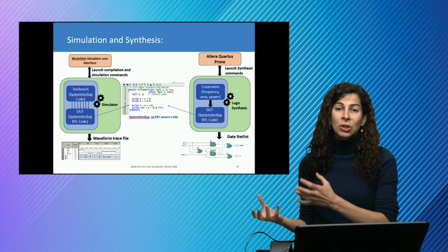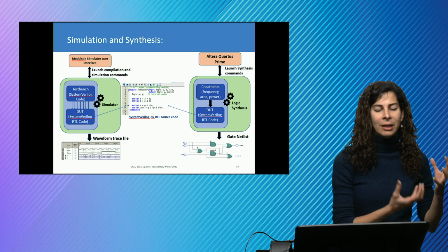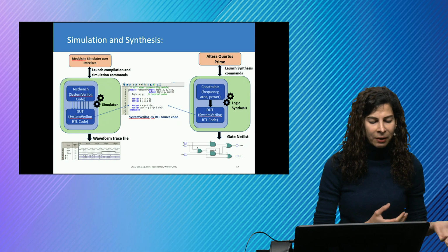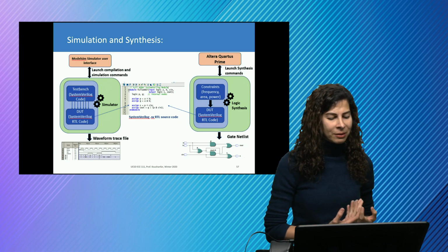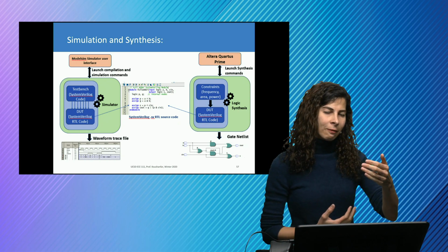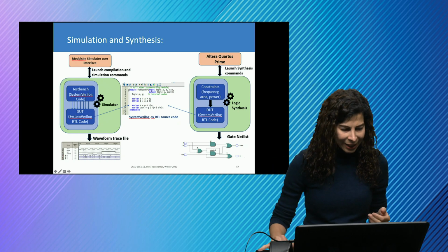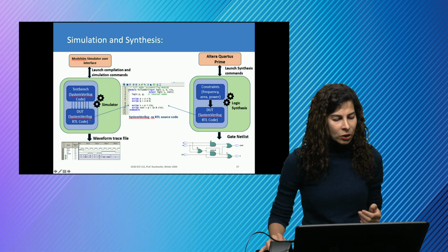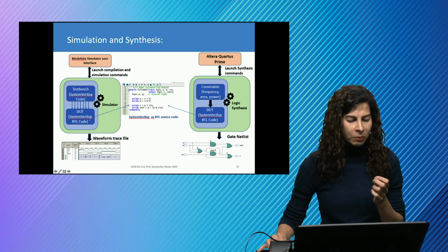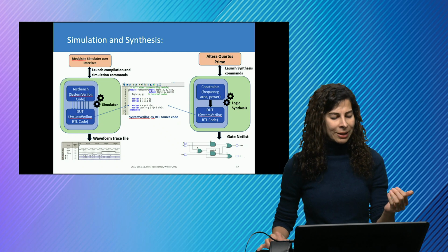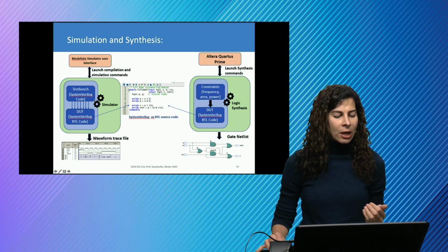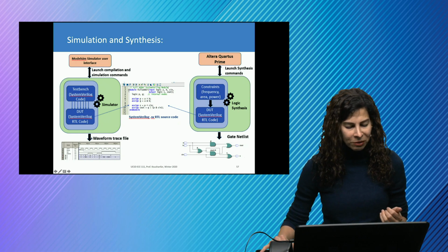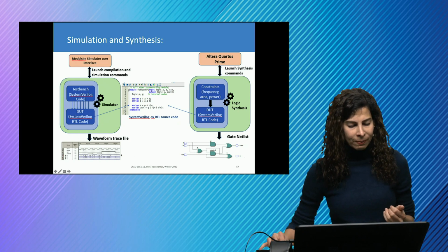And physical implementation assumes that we've taken care of the design earlier in terms of testing and verification at a higher level. So typically, this ModelSim simulator not just has System Verilog code, but also has test benches and uses part of the design as a design under test. So we have some code that is only used for testing in the simulation phase to make sure that things are correct, and also have the ability to see the waveforms in the simulation phase.